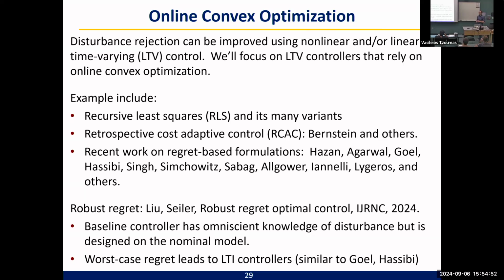These regret-based formulations would say, well, it would be better if I try to optimize relative to some baseline. What baseline? Well, suppose I knew the entire disturbance ahead of time and I designed the controller with perfect knowledge of the disturbance. That's like a non-causal controller, because I tell you the entire disturbance ahead of time. And then I'll try to optimize my controller.